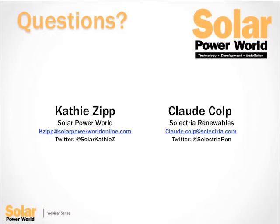So in that case, it's likely that we're talking about a combiner box and larger central inverter kind of configuration. I'm only assuming that we're talking about commercial utility scale projects at this point regarding that. But in that case, the Arcom combiner box would be deployed within 10 feet of the subarray, and the output conductors would be run to the inverter location and sized for voltage drop. Okay.